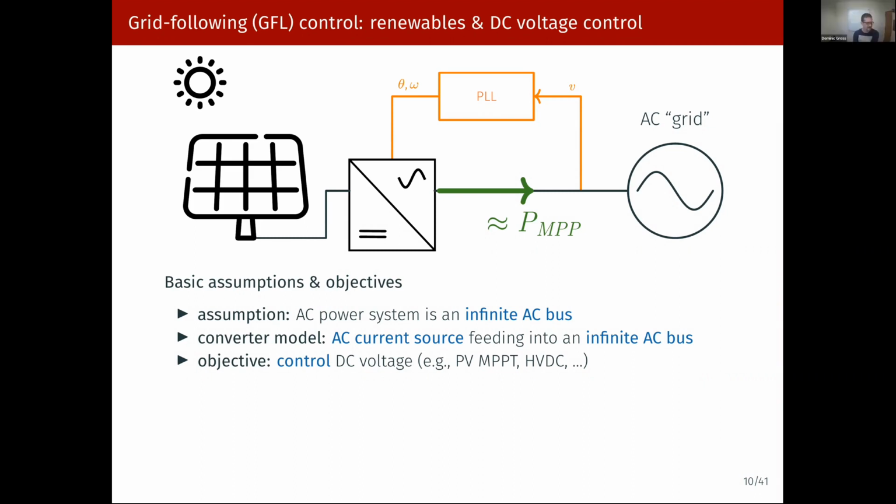And then there's certainly an analysis and stability certification problem, because the way you're ensuring interoperability and stability of these things right now is that you basically just run massive simulations, right? And you run a ton of different case studies. And that's fine if you have a few hundred of these synchronous generators in a system like the continental European system, and you can come up with a good reduced order model that has maybe 20 generators in there. I mean, then it's feasible.